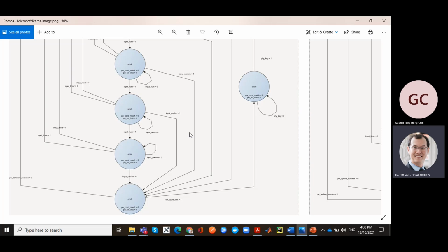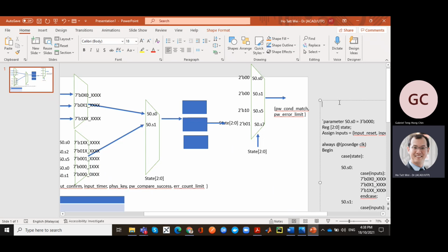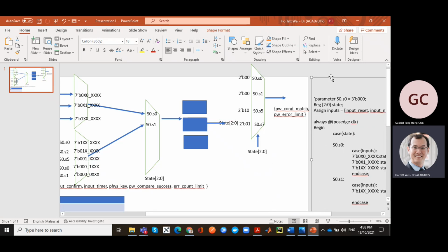So based on this, same argument, you can write the case statement for this. There are two ways to do it. One would actually be to use what we call a sensitivity list. I don't like this way, but it's a bit more competent. I like the other way. This way is basically you have to look at all the possible inputs. State is the only possible input, so whenever any bit of state changes, the output will change. But the problem is if you miss even one, you will synthesize a latch, and then you have weird bugs. I don't like to do it this way.